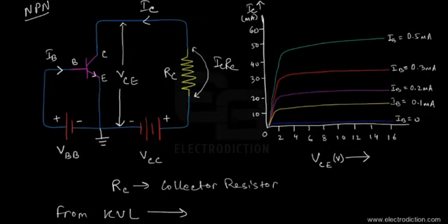Now what I'm trying to say is, for instance, if we keep the input open circuited, so that the bias voltage source VBB is not connected to the base terminal anymore, then it's quite clear that we wouldn't have any forward bias voltage drop across the emitter junction. As a result, the BJT would be sent into its cutoff region.